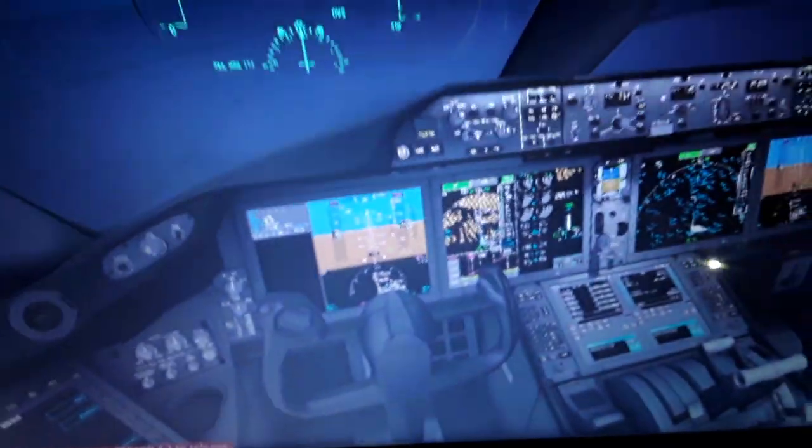So as we climb higher, the FADEC, the full authority electronic control computers, one installed per engine gearbox, one in the left wing, one in the right wing, dual channel redundancy, if one channel fails, the other takes over. So it controls all the functions that I told you. Also the fuel-air mixture, as we climb higher, we have a higher intake of air from the front fans, so it's adjusted automatically. Also as we descend back to the airport elevation.